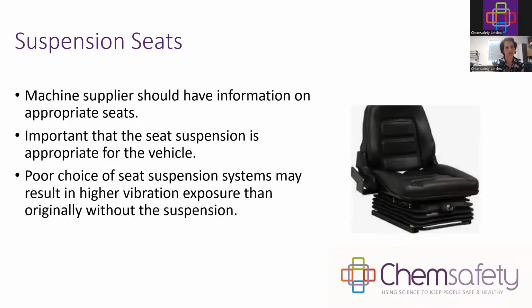And then suspension seats, there's quite a lot on the market. It is very important, when you're opting for a good suspension seat, not to go for the cheapest option, because many times a poor choice of seat suspension can result in a higher vibration exposure. So if it's not sturdy enough or it's of poor quality, it might cause more vibration and just exaggerate the whole problem.